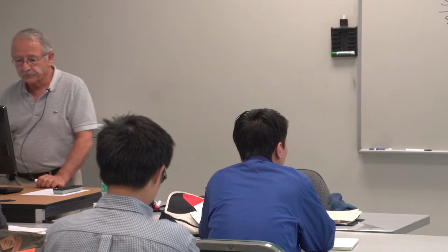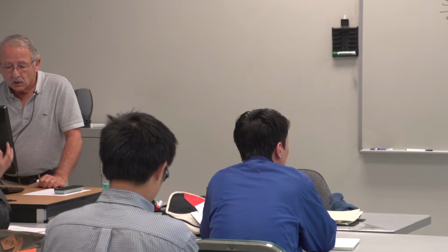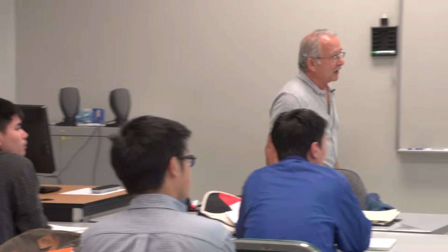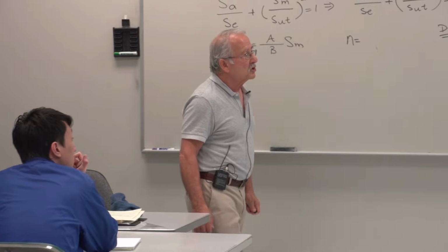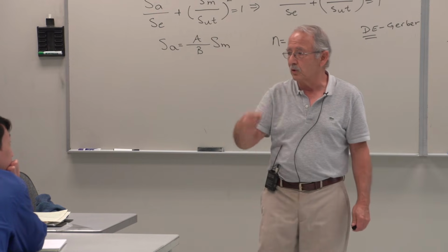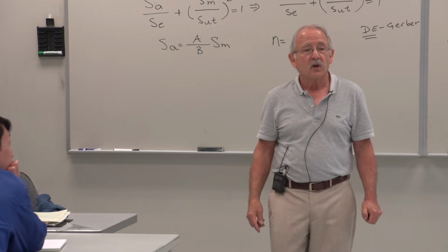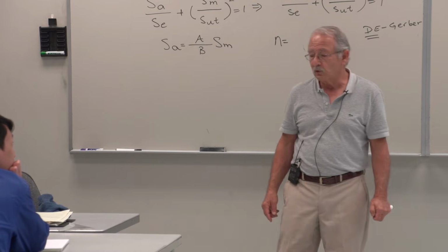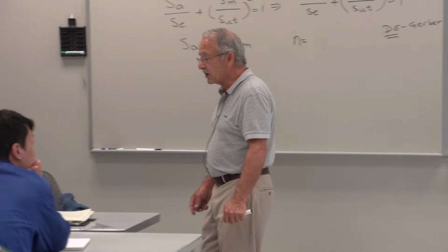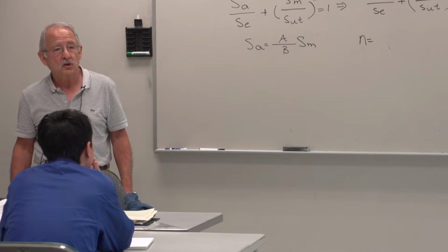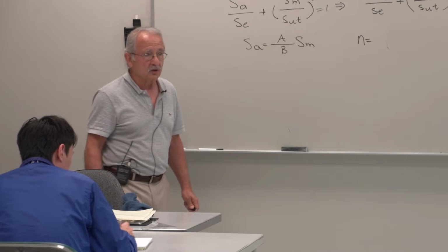And we must make sure that the natural frequency of the shaft and the frequency of the applied load, that would be the frequency of rotation, never get close to one another. In fact, we would like the frequency of the shaft to be at least two times that of the externally applied load.